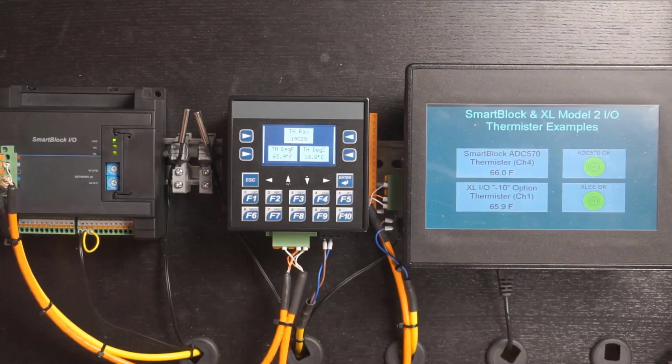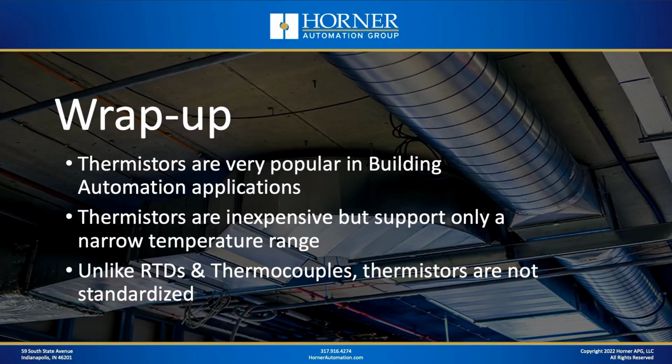That wraps up all the material I wanted to share with you today. Let's do a wrap-up. The important points today are that thermistors are very popular in building automation applications. They're very inexpensive. They only support a narrow temperature range, but for HVAC and building automation, that's not a problem. Unlike RTDs and thermocouples, thermistors are not standardized, so be careful which thermistors you source. If you're using them with a Horner controller, choose from the Kiel or the YSI. Those are widely available, very inexpensive, and they'll work extremely well with the Horner controllers.